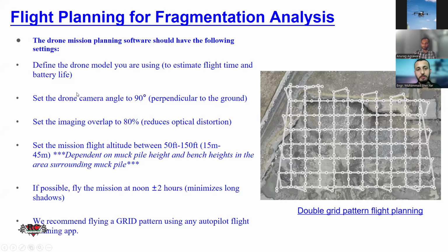First you need to define which type of drone you are using as per the type of result you want. So you need a better understanding of the different models of DJI drones, and also of the perpendicular camera, like you need to capture the oblique pictures at 90 degrees, and set the overlap up to 80% using the DJI Matrice 4 series, specifically Matrice 4E. The overlap will be reduced? Yeah, you can keep it at 75, just to save time.